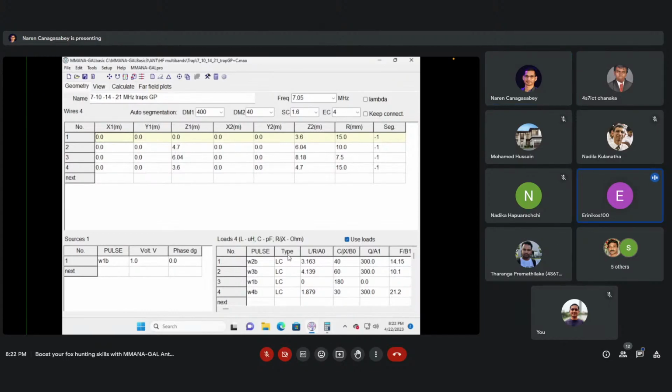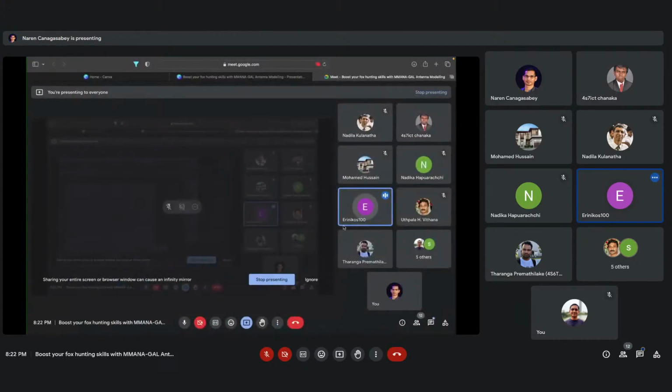Honestly, I don't know how to do it. It's complicated. I haven't tried it. That is possible. But a simple answer to the question, yeah, you can do things like impedance matching and add a trap coil, like Naren said. So you can design a dipole and add 2 trap coils and keep changing your LC ratio until you trap a certain frequency and design a dual band dipole antenna. So yes, you can do it. Okay, Ron. Thank you.